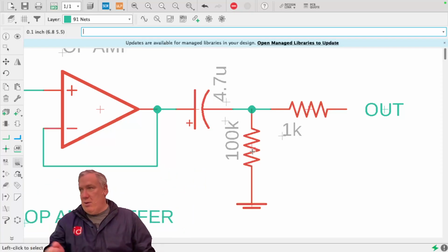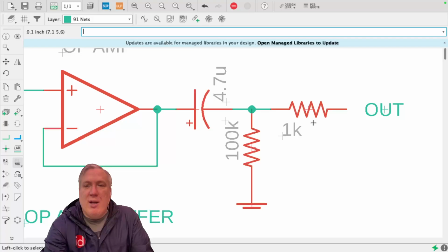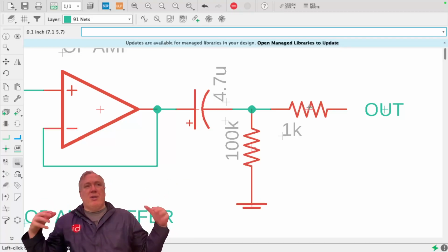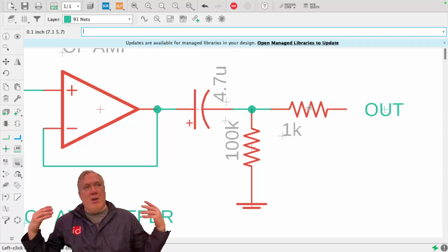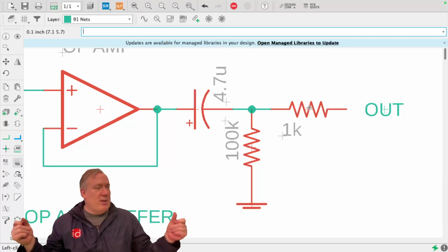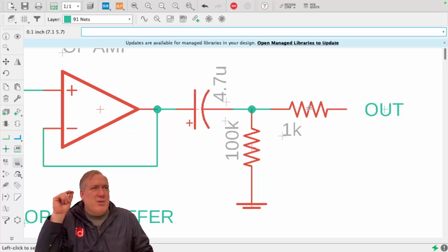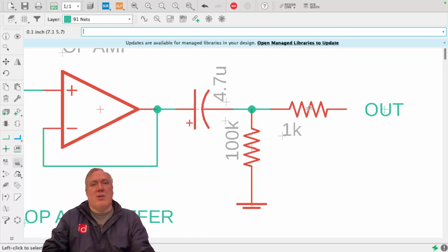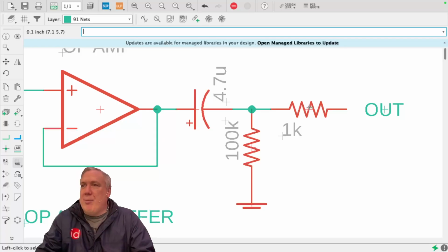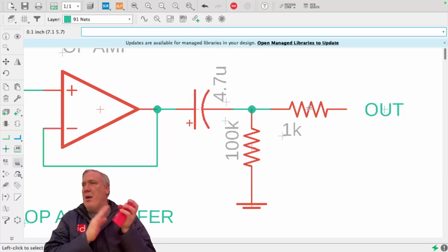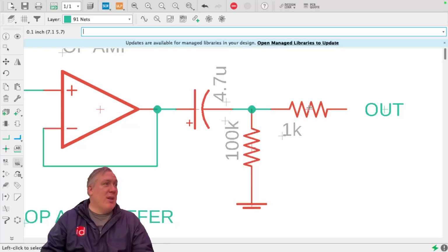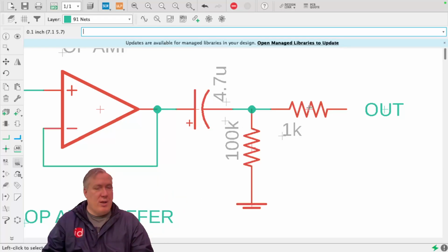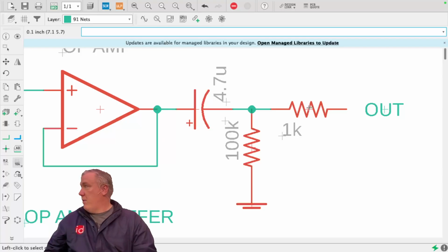Okay? And then this resistor, and the reason why there's a resistor on both ends, it slows down the amount of current that can happen in one moment. So even if there is still a little bit of voltage, that voltage doesn't travel as fast because it doesn't push as much current. So it doesn't make as much of a pop. And so this is all about making it so that when you turn on and off your pedal, it doesn't make your speaker make a loud pop. That's what it's for.